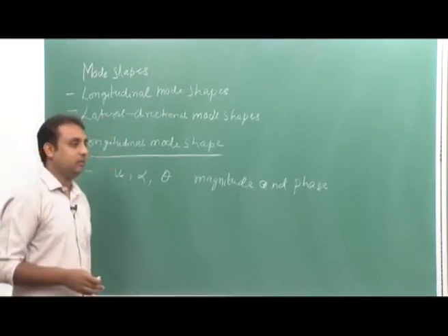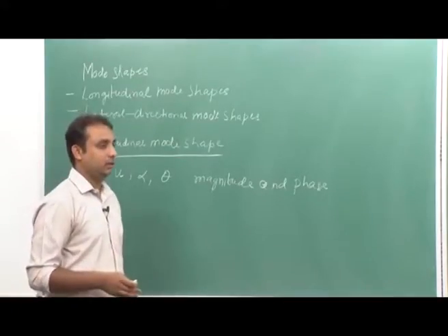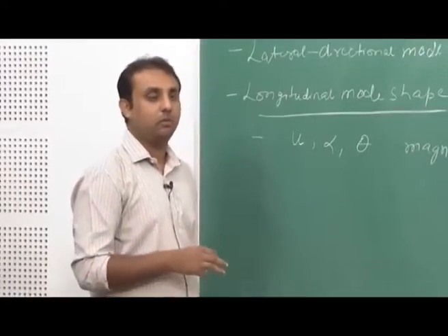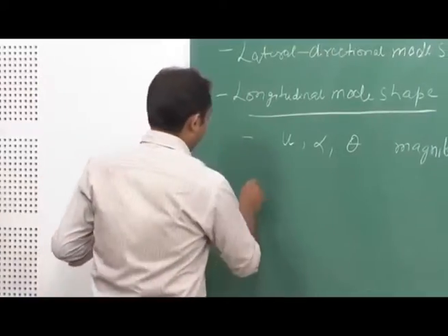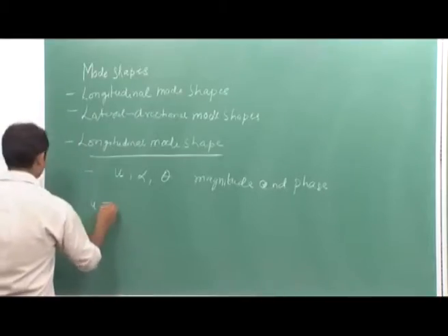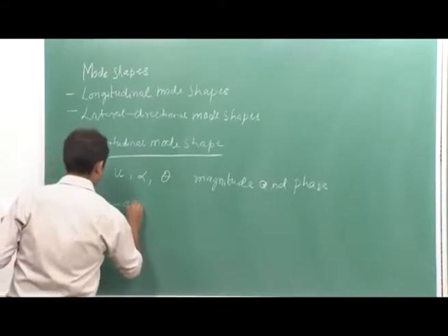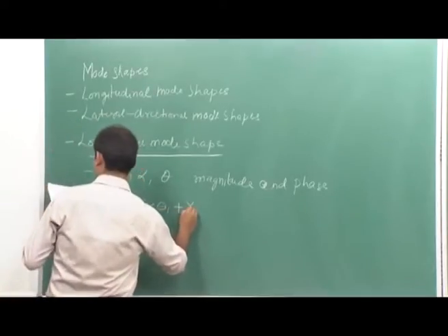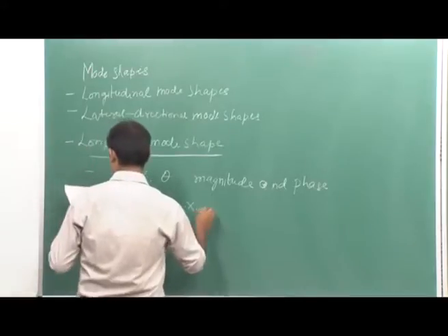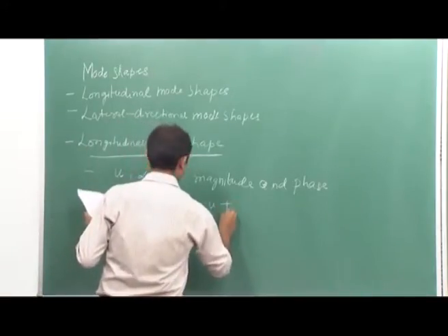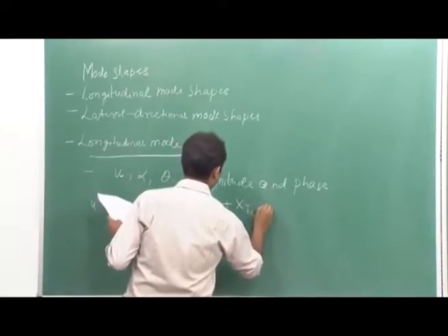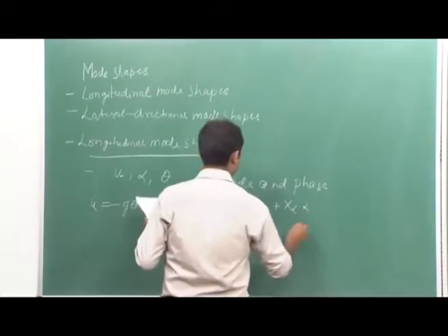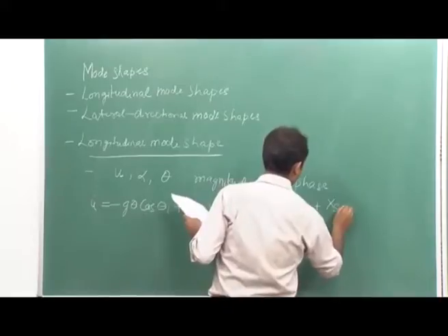As we have already seen while deriving the transfer function and the various modes of longitudinal motion, the differential equations for longitudinal motion were: u dot minus g theta cos theta 1 plus x u into u plus x T u into u plus x alpha into alpha plus x delta E into delta E.